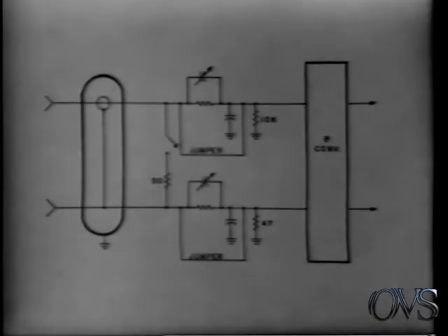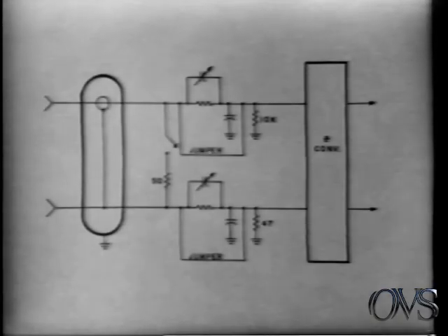Next, let's discuss the X and Y axis deflection circuits. The inputs are fully differential. A triaxial cable is used, with the center conductor going to one side of the input, the shield going to the other side, and a grounded shield around both of these. Instruments are shipped in a single-ended configuration, but are easily changed to differential operation by changing this resistor value from 47 ohms to 10 k ohms.